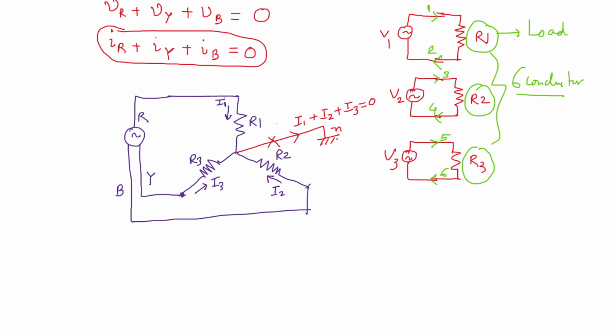So instead of applying three different loads from three different single phase supplies, if we adopt a three phase supply, we can deliver the same amount of power using only three conductors. That is the biggest advantage of the three phase supply system over single phase supply system.